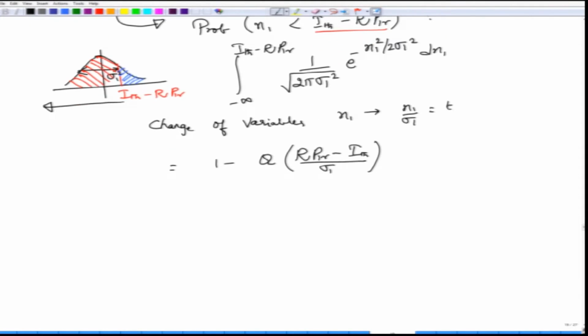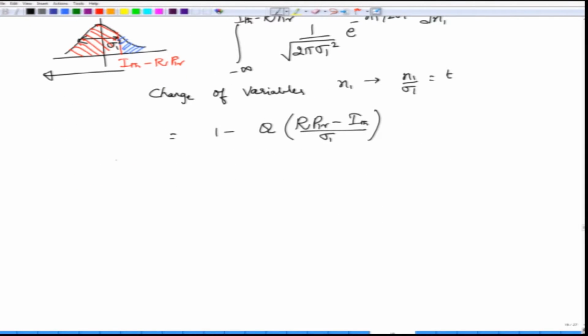Once you have done that, now you can put together the total error. How do you put together the total error? Suppose you have bit 0 and 1 in the on-off keying, that is what we have. When you transmit 0, there is a certain probability that the receiver will identify that 0 as 0, which is given by probability of 0 given 0. However, this is what you are interested in: so this is 0 and 1, the probability that the receiver has identified it as a 1 although you transmitted a 0.